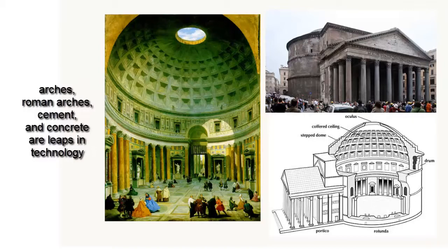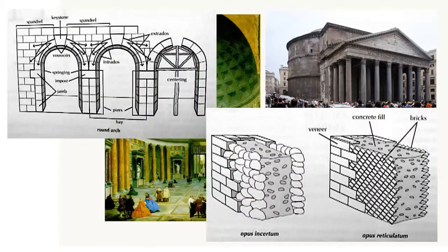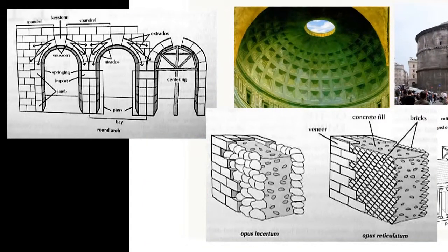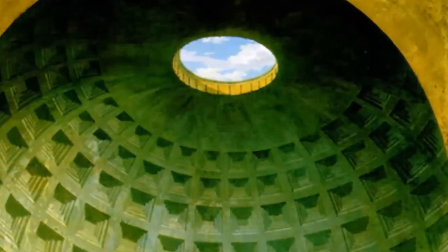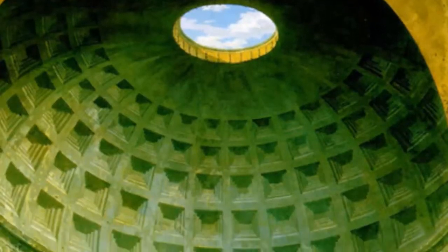So they were able to make a building using cement, which they figured out how to make slower drying, and use what's called a Roman Triumphal Arch and rotate it 360 degrees, in which you then have a keystone in the oculus, which is that skylight in the top, called an oculus for the eye, and it locks up and it uses this sort of tensile strength of the structure leaning in on itself, along with variations in concrete to make it hold up together. The other way that they do this is with the coffers.